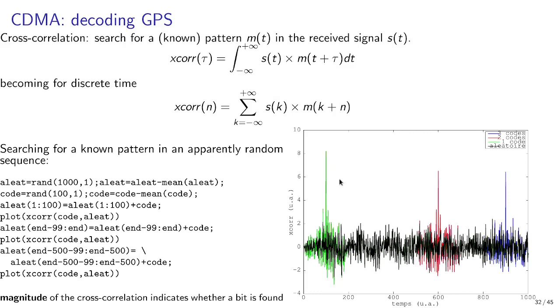This will lead to a brute force approach where both frequency offsets and code must all be tested. There are 32 possible Gold codes, for up to 32 possible satellites in space. So we must know what frequency offsets we must consider to compensate for the GPS Doppler shift.